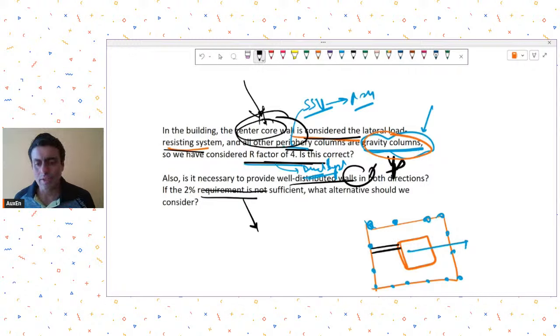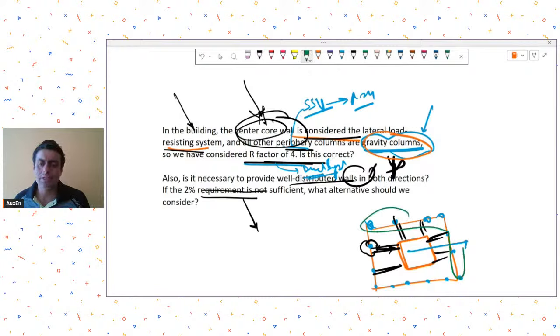Also, because then you will have to introduce some elements to transfer the loads to the central core wall. So again, if that is the case, this column you cannot leave as a gravity column. It has to take some effects of the earthquake movements also. So I am not very convinced with the type of system you are proposing. If at all you want to give only centralized cores, have this system as an SMRF at least.